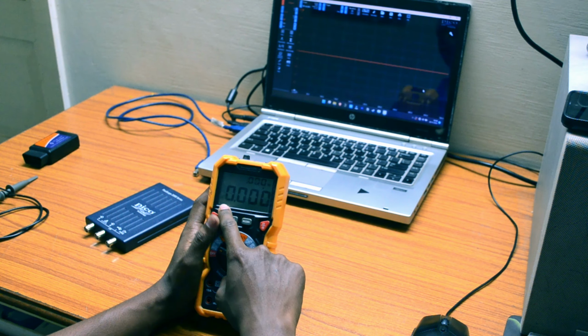And the next one is millivolt measurements. When we are measuring very low voltages, this will help in getting accurate measurements such as 20 milli or 30 milli or 80 millivolts. The next one is frequency measurements. Usually in AC voltages or analog voltages, the voltage will keep on fluctuating, that is on off condition, or from positive to 0 to negative. In those signals we can measure frequency. And the next one is resistance measurements.